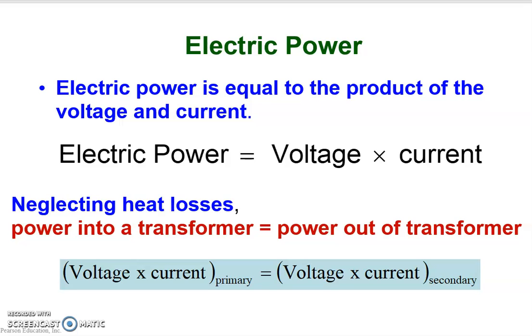So in order to explain why we need the transformer, when we pass the voltage from the power plant to your home device, we have to introduce the concept of electric power. Actually, we already learned the concept of power before. It is the energy spent per hour or per second, depending on the unit. So the electric power is actually the voltage drop multiplied by the current.